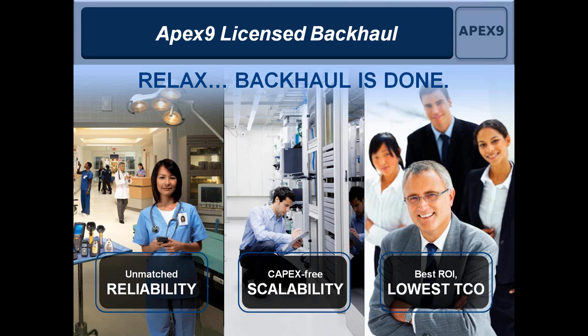But to summarize, Category A and Category B define the dish size that you need to license your Part 101 backhaul link. So under the current rules, for example, 6 gig requires a 6-foot dish to fall under Category A. But with the new updated report and order that came out, they now allow for a 3-foot dish. So when talking about Category A versus Category B, it really determines dish size. So if you're deploying a link and you don't want to ever worry about any sorts of changes or updates on that side,